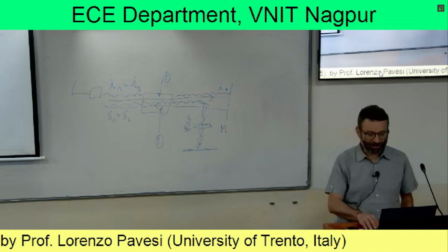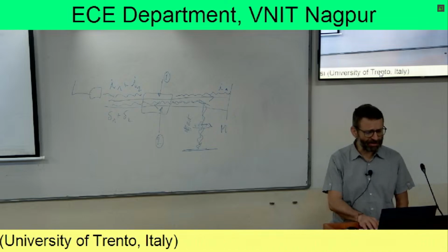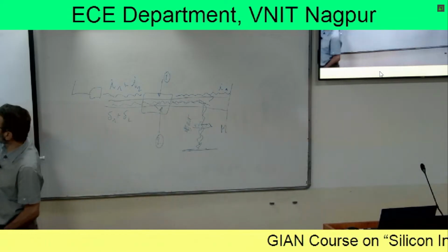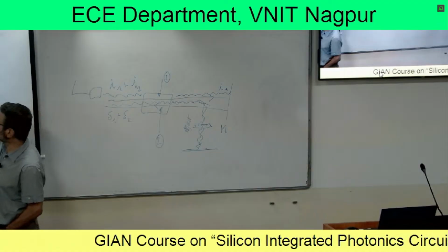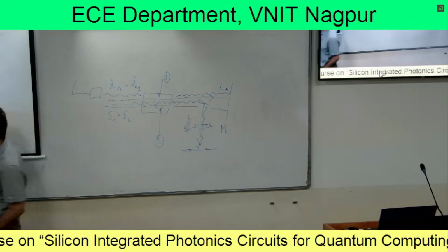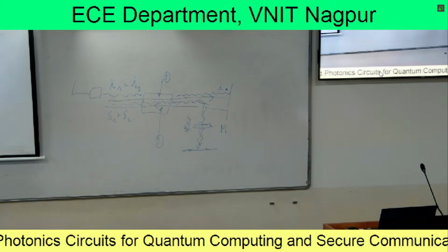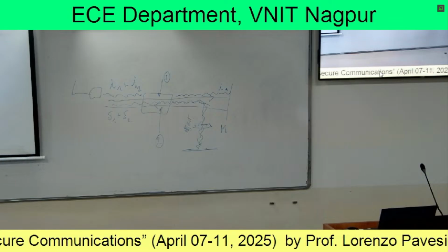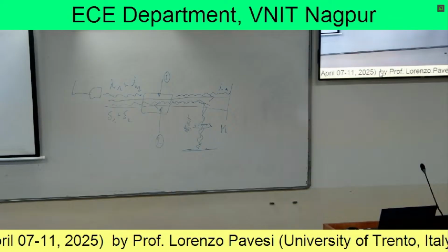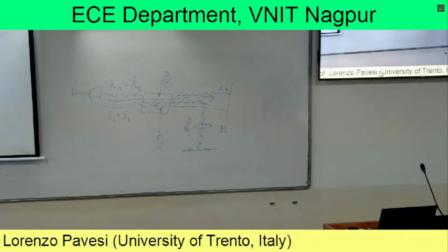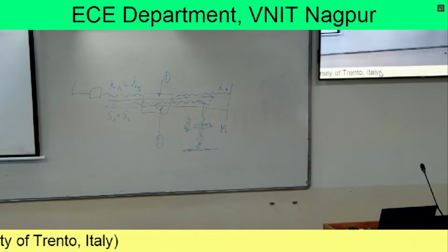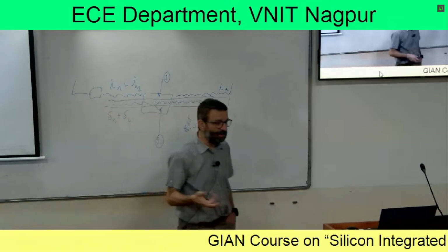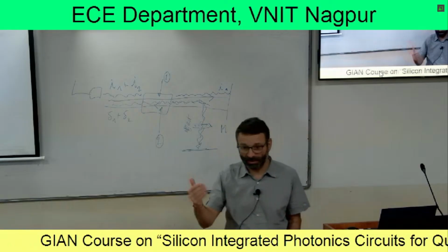However, they are all multimode. So in this experiment, here you find all the details, but the one where we are able to get these very high numbers here, this waveguide here is a multimodal waveguide, because this is a single mode. But the chip was fabricated with very high quality processing, by which the propagation losses, I don't remember exactly the number, but should be in the order of 2 dB per centimeter, extremely low.